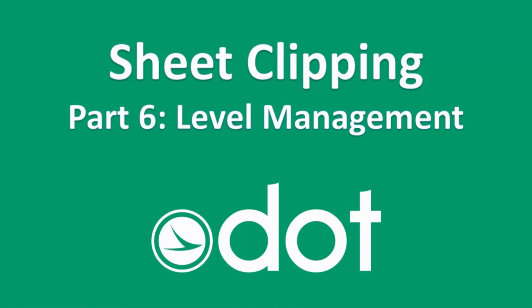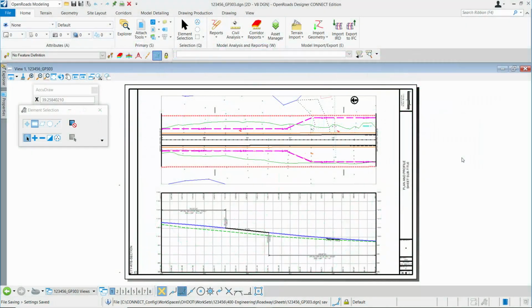In this video, I'm going to talk about managing the levels that are turned on and off in our plan and profile sheets. To get started, I have a sheet open with both plan and profile views, and the profile view is actually okay. So I'm going to focus on the plan view, but the procedure would be the same if I were turning on or off levels in the profile.